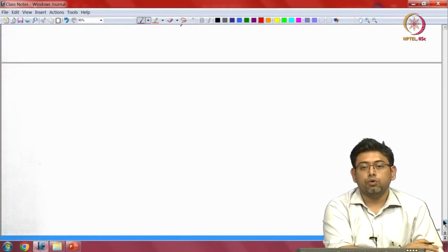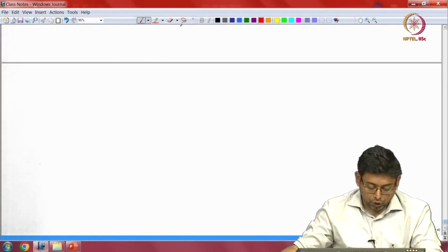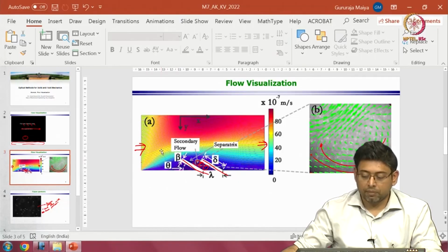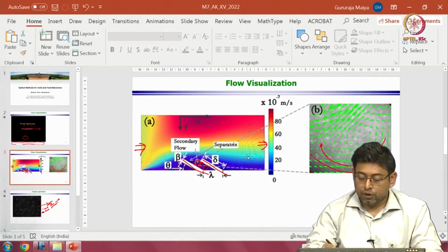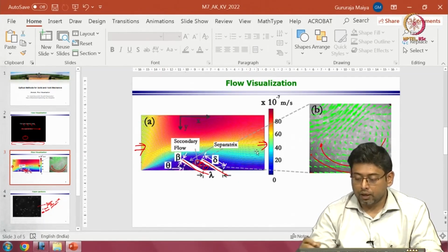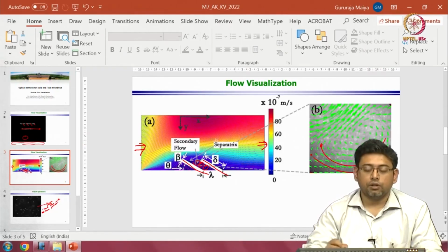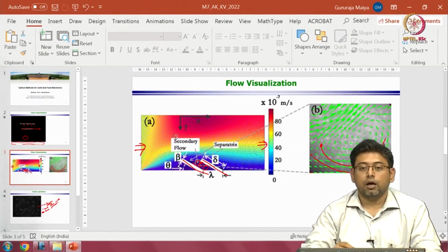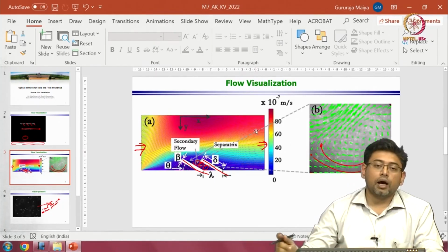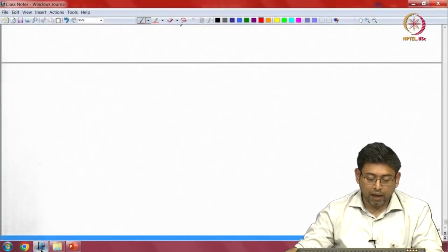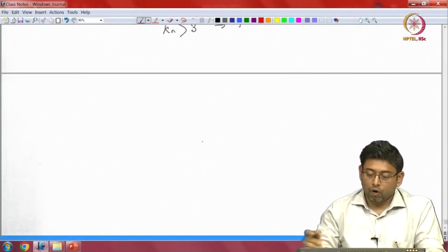But once you do that, just like we showed you here in this particular image, here you have in the red, what you have are the fluid streamlines, which by the way have to be computed. In a given experimental technique, what you usually will get is the Eulerian velocity field. From this Eulerian velocity field, you will have to create these streamlines. You can also create other visualization lines such as the streak line and the path line, and we will just quickly go over them as well.